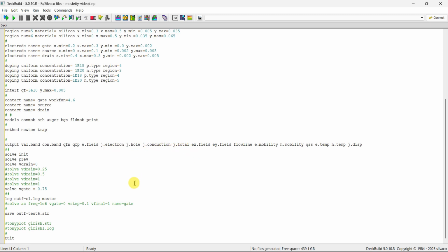The simulation then applies 0 volts at the drain at first, as we have to design this for five cases with different V drain values for the comparison of conduction band energy. So the code works for only one V drain value at once. So we have to comment out other V drain values like this.